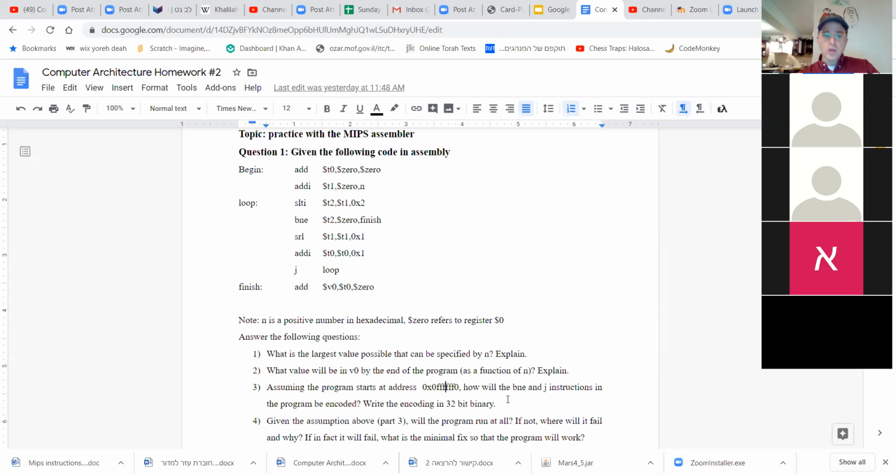So the computer won't realize that, right? It will just go forward. Yeah, exactly. The computer won't realize that, and it will go to the wrong location. No, it won't go to random. It'll go to the wrong location. Instead of going to FFFFF, it'll go to 01 FFFFF. In other words, it'll change the bits that it can change, and the bits it can't change, it's stuck with, which will be a 1 over here. So instead of going backwards, it'll go forward.